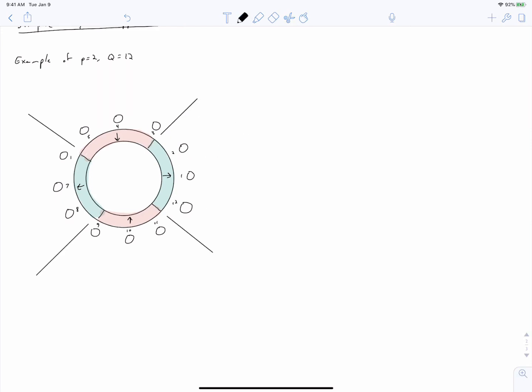I've sketched this with a 4-pole permanent magnet rotor just to help make it a little bit more obvious what we're doing, although we're talking about the stator. I've then drawn circles for each of the slots. We're going to fill that circle with a cross or a dot to indicate the direction of a coil side, and then we'll place a label of a U or a V or a W to indicate which phase the coil side is assigned to.